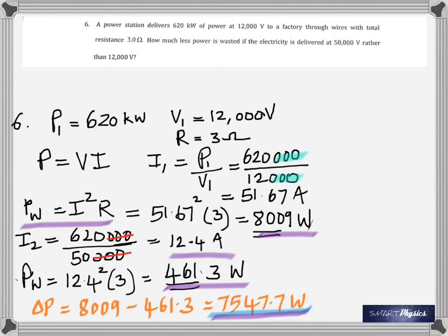Now, I think you appreciate that voltages must be really high. That's why the line voltages are really high. But before it's brought into our homes, it's stepped down to 120 volt. From the generating station, when it comes through the lines, the voltage is really high. The reason? To keep the current low. When the current is low, the heat produced is really small. Otherwise, we would not get any power in our homes. By the time it reaches our homes, all of it is gone to heat the birds and the atmosphere, and it's all wasted.